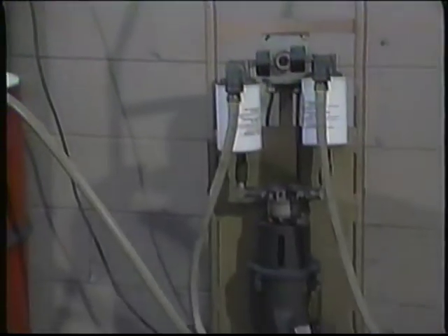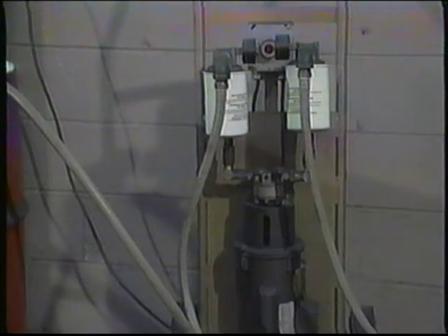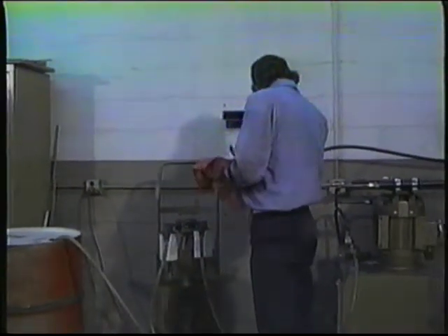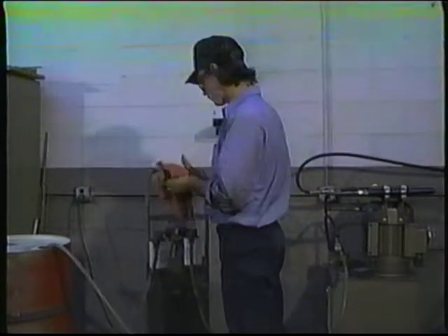If you have a system which requires, say, 25 micron filtration, then the fluid from the drum must be filtered before it goes into the system. You should make sure the transfer pump you use provides adequate filtration for the system. Otherwise, even brand new fluid can cause operational problems.